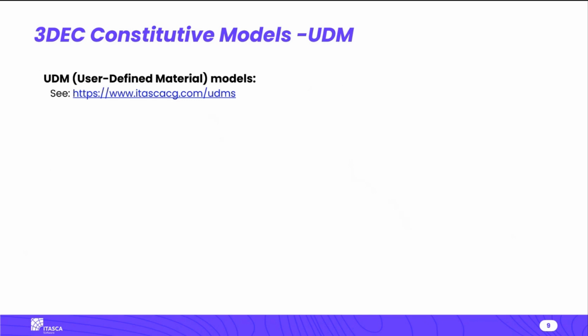It is also possible to create your own constitutive model. This is fairly common in soil mechanics, where people have different interesting behaviors for different specific soils. In the rock mechanics world, this is less common. I don't see this a lot in 3DEC. However, it's also possible to create your own constitutive model for the joints, and I'll talk about that in a future session. So I won't go into detail here about how to create your own model, just to let you know that it is possible, and it is described in the documentation.